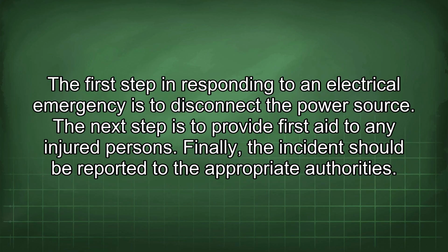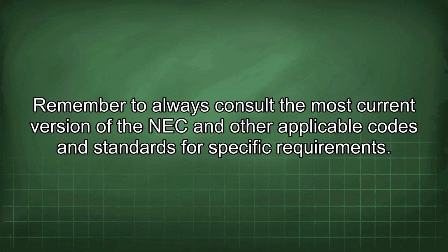The first step in responding to an electrical emergency is to disconnect the power source. The next step is to provide first aid to any injured persons. Finally, the incident should be reported to the appropriate authorities. Remember to always consult the most current version of the NEC and other applicable codes and standards for specific requirements.